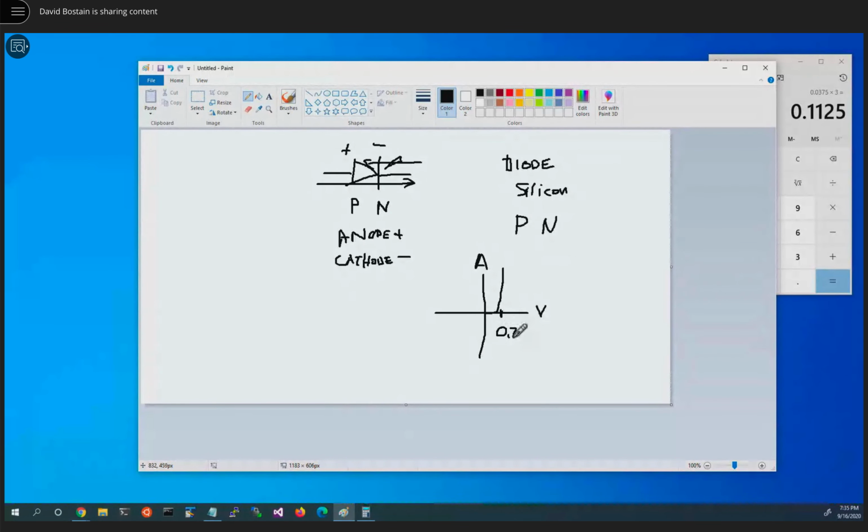I told you earlier in the semester there were one or two places where we don't put it in engineering notation. This is to please the engineers because they call it 0.7 volts. But at roughly when we supply 0.7 volts, if we continue to apply voltage, it'll increase the current much faster than it can possibly increase the voltage. So we would get almost what we would consider very forward bias. Basically, the diode goes away. It has 0.7 volts dropping across it, but any amount of current we give it, it can pass it.